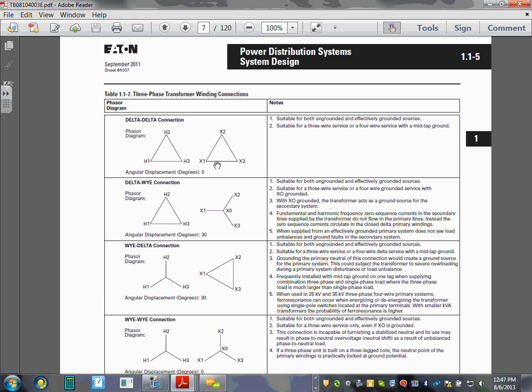Though you can go delta delta, we use this system if you have an assembly line and you don't want the assembly line to stop for any reason, like we talked about grounding. So if you have a ground fault in one phase, the system will continue to operate properly until you schedule a maintenance time and get rid of that ground fault. So that's the first system. Typically we use it for survivability. This one is the most common one, like I said.